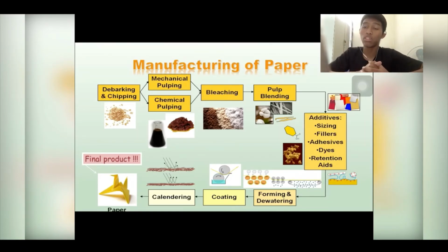Other materials used in paper manufacture include bleaches and dyes, fillers such as chalk, clay or titanium oxide, and sizings such as rosin, gum, and starch. So let's talk about the manufacturing process. For making pulp, several processes are commonly used to convert logs to wood pulp.